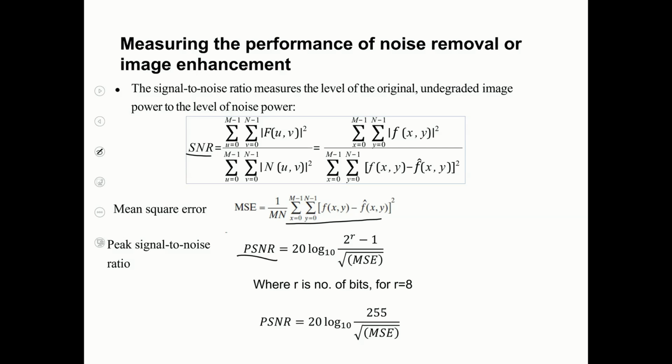Okay. Then we also have PSNR. PSNR is like SNR, but in the denominator it's the maximum power, the peak power of the image. I know that for an 8-bit image the peak is fixed, so the only thing I need here is the mean square error. So it's like peak divided by the noise power. Okay, that's it. So these are three terms.